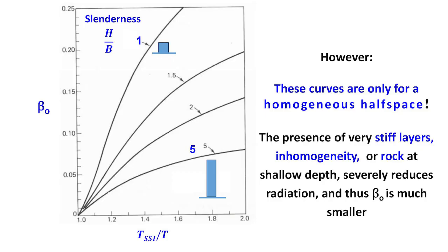This effective damping is significant only for structures which are not slender, squatty structures, H over B of 1. Why? Because the horizontal shearing, not the rotation, is the dominant. And in horizontal shear, the damping is very significant. You remember which I mentioned in the previous one.